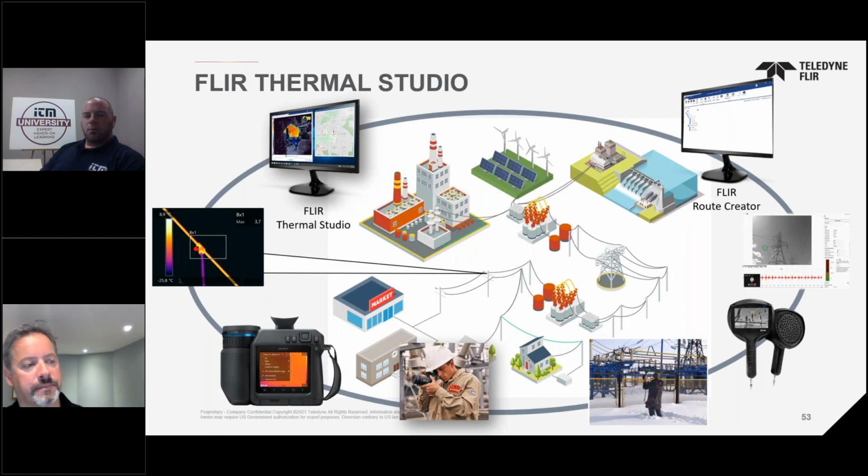Is there a possibility to use the acoustic imager to detect an electrical motor failure or a gearbox failure? Yeah, if the motor is vibrating, which means something is out of balance or the bearings are failing, they start generating ultrasound. Actually, that's one of the quickest ways to check bearing failure, because you can see it right away. What's nice about an acoustic imager versus a thermal imager is that if you lubricate the bearings, the frequency is gone, or if you rebalance the motor, it's gone. So you right away know that it's fixed.